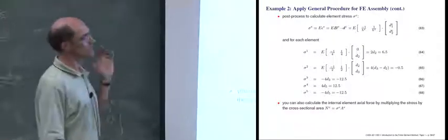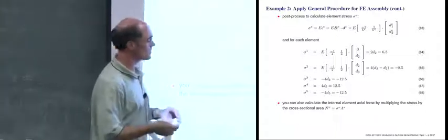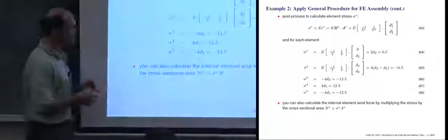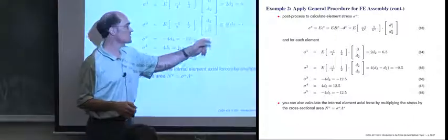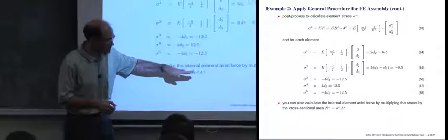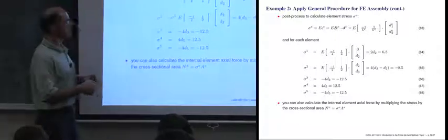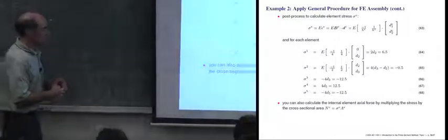Okay? So you can see how the finite element method approximates something. For certain instances, not only the values of the displacement for this example happen to be somewhat non-physical, but this constant stress and constant force may also seem non-physical.